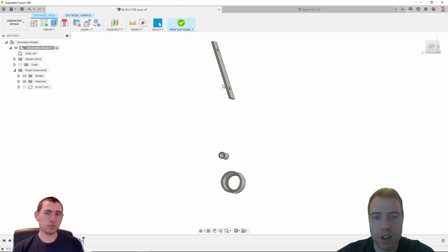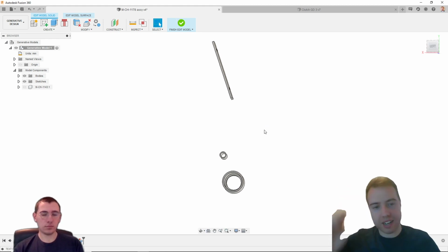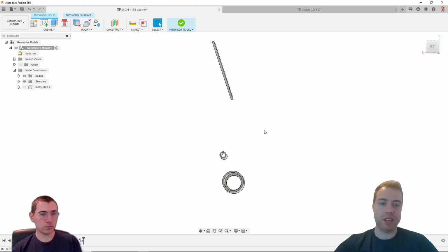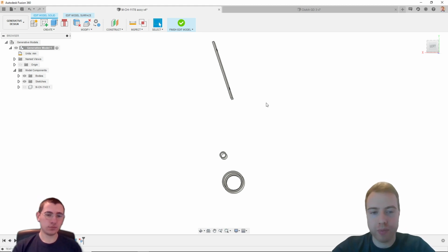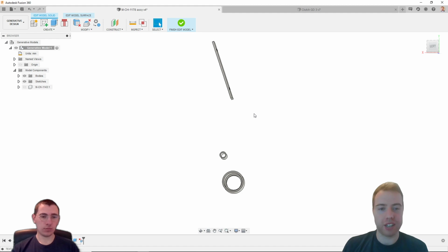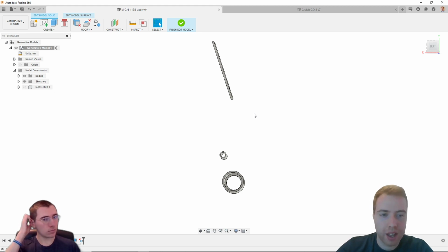Okay, so once we've created this preserved geometry, the next bit of geometry we create is called obstacle geometry. This preserved geometry, we've defined for generative design, are the regions our final design needs to have in order to perform its core functionality. And our obstacle geometry is going to be, we need to let generative design know that there are areas that it can't go into, and there are spaces that it needs to keep clear of geometry that it creates.